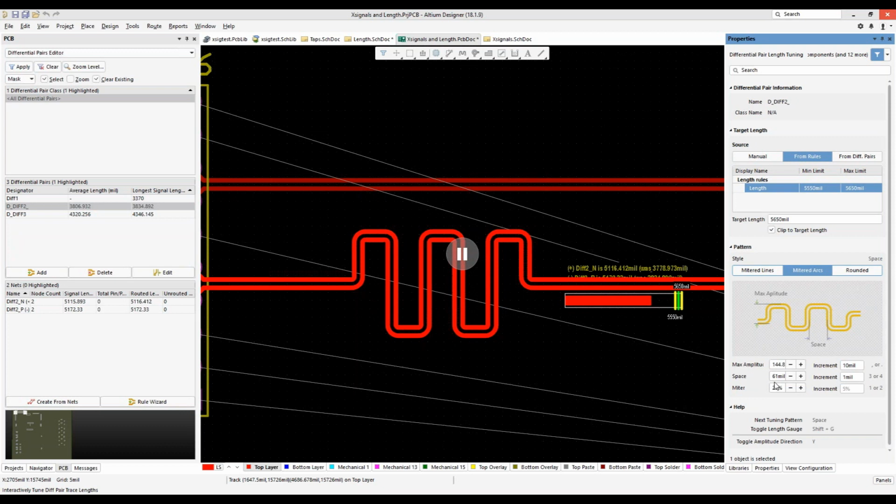The one thing I'll mention about the spacing is you want to be careful about it, because in high-speed design, you can couple onto your own wires. So if these wires are close enough to each other, usually the rule of thumb is that if they are less than 2 trace widths, you might have a coupling opportunity over here, even though they are the same wire. So be a little bit careful about your spacing.